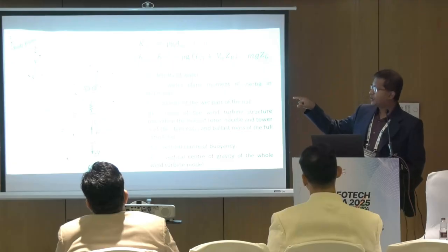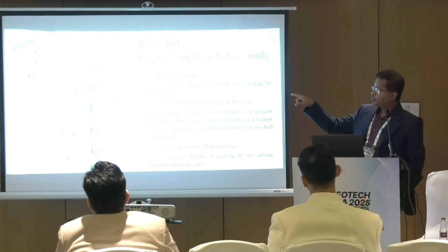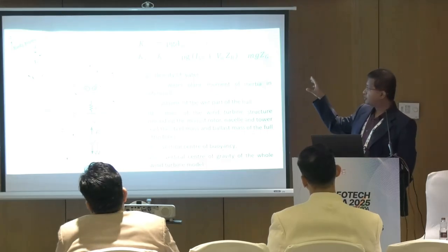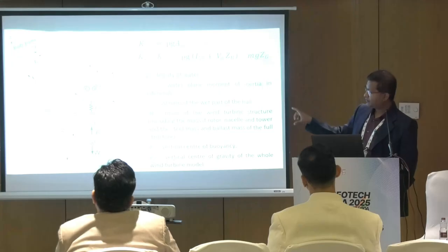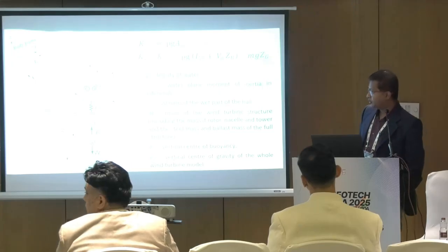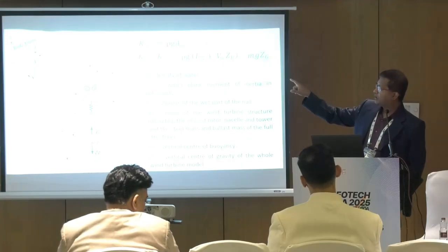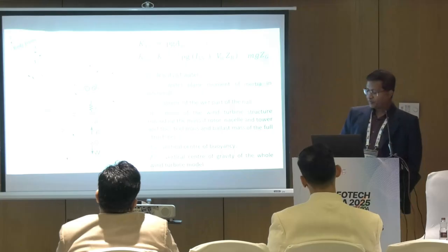So these rotational springs are basically the hydrostatic restoring forces, which are incorporated in terms of the rotational springs. And those spring stiffnesses are calculated based on the various important parameters related to the geometric properties of the structure as well as the properties of the fluid. The first one is for the heave motion, and the other two are for the pitch and rolling motion, that means the rotational motion.